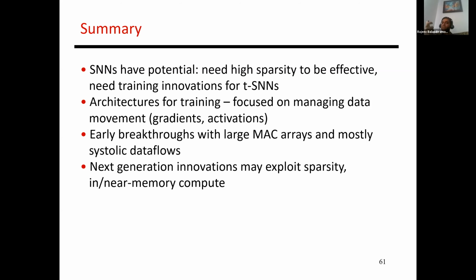There are papers from the IBM TrueNorth team that show that with their neuron model, you can configure the neurons to emulate each one of these Izhikevich models, right? And sometimes you may need 2 or 3 of their basic neurons to implement one of the Izhikevich neuron models, right? So it is possible. They're essentially coming up with the basic primitives that use LIF, that use some stochastic features, and using those, they can be configured to do more, right? And I think that seems like a reasonable way to do it. This is kind of like the RISC-CISC approach, right?